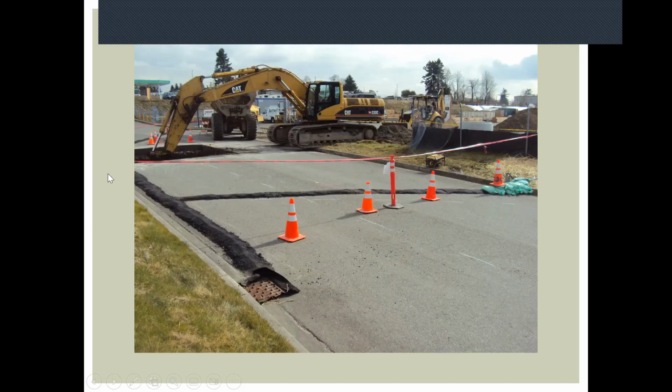So you drive up to this site, see what's going on. They're excavating, they've got asphalt berms directing clean water away. They're collecting the dirty water inside and they're pumping it. So this is a great practice contractors are using. I would just say, check to see where they're pumping to, that they're not pumping to another catch basin. In this case, they're pumping to a hole back on the project. So that's a good thing.